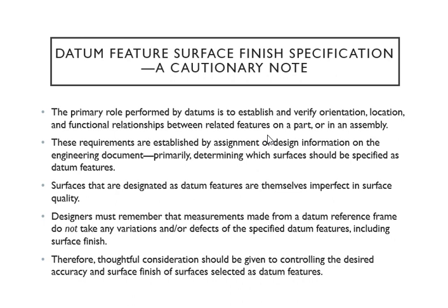In order for the fit to be successful in your assembly, we use the datum to check the measurements are accurate. Otherwise, your bolt will not go into your hole, and the first part will not go into the second part. You have your circle diameters, which are all holes anyway. So the holes gotta fit into each other.